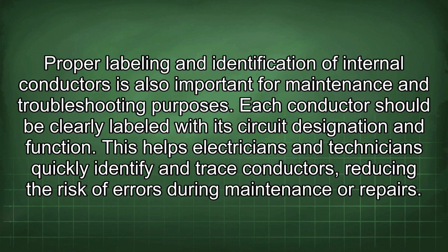Proper labeling and identification of internal conductors is also important for maintenance and troubleshooting purposes. Each conductor should be clearly labeled with its circuit designation and function. This helps electricians and technicians quickly identify and trace conductors, reducing the risk of errors during maintenance or repairs.